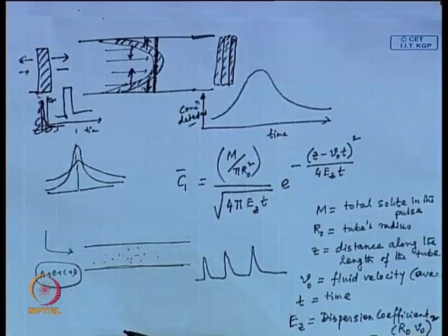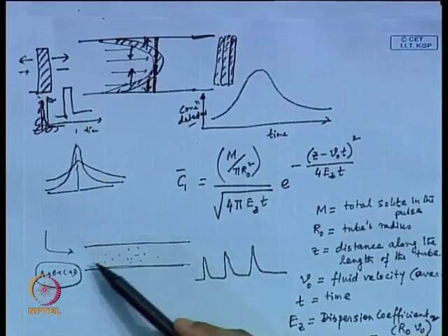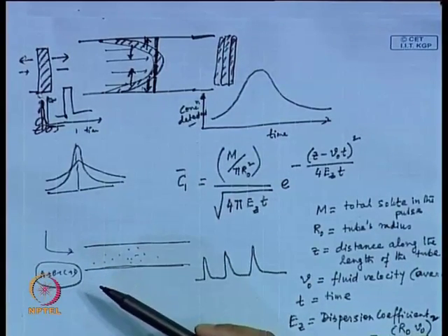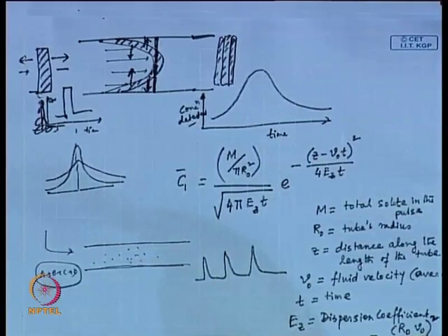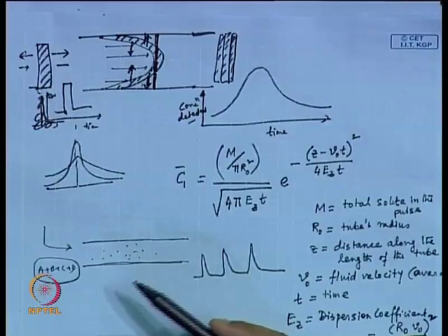Now, in a microscale process, you do not expect the beads to be there. Two ways it is accomplished. One is, you have a microchannel with a wall coated with adsorbent, so the wall acts as an adsorbent. Or it could be that you have a monolith, because a small packed bed is not very common. You have a monolith structure, which is more like a honeycomb. It is already inbuilt; the entire passages are built in an integrated structure. It is not like you take a tube and then take a pack of beads and fill it there.